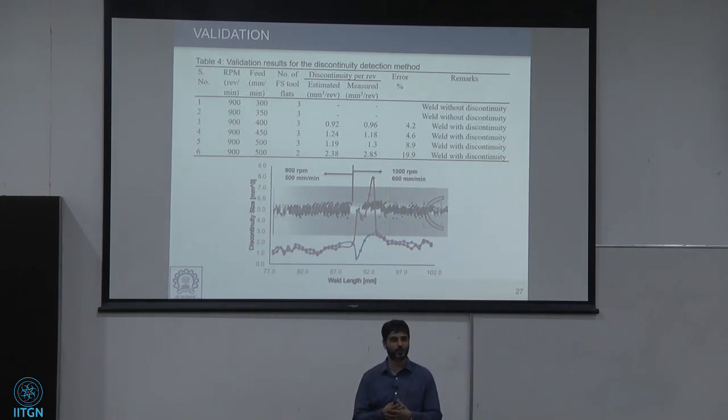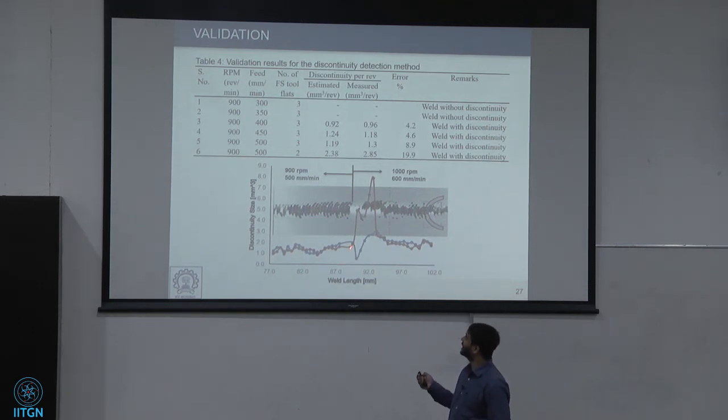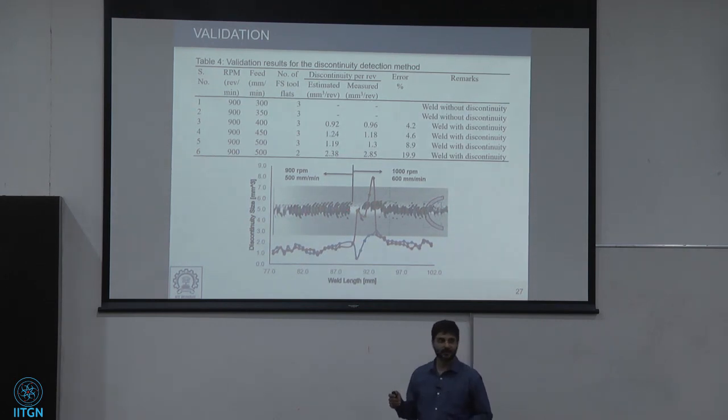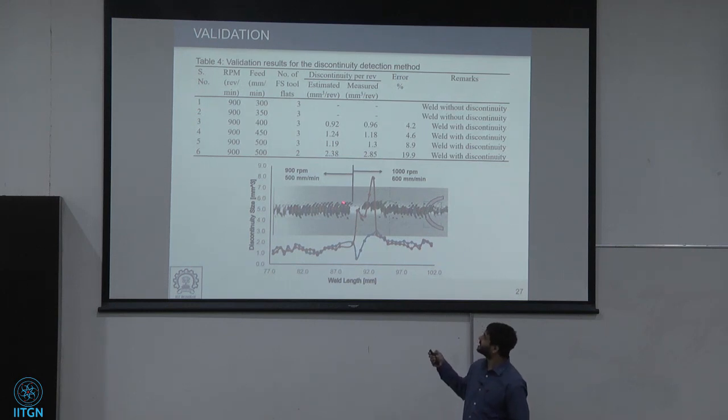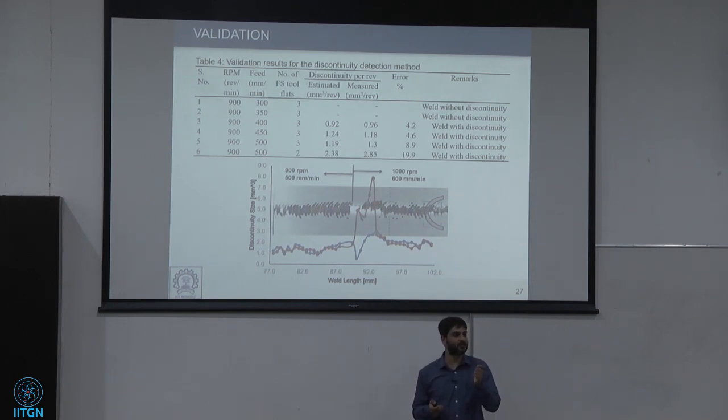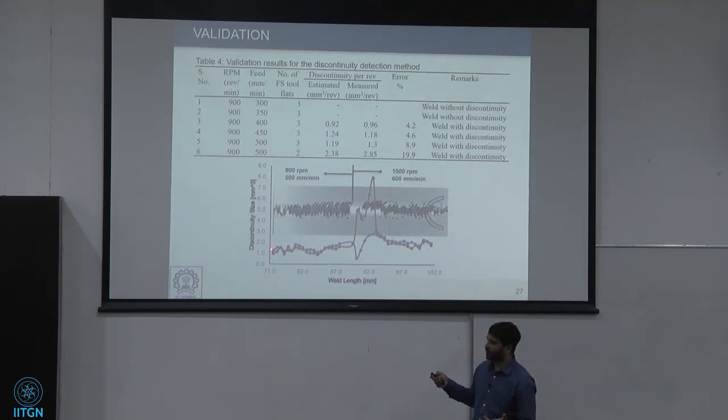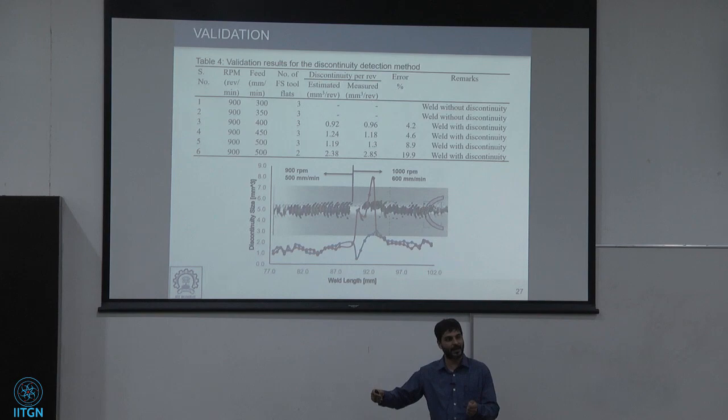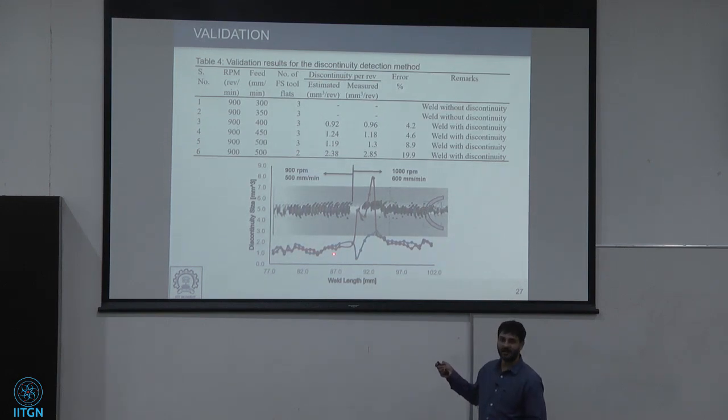Then, with the help of the observer approach, which was developed previously, we applied the same algorithm to the observer in real time, and we can see as the defects are formed. So for this particular weld, we identified in the CT scan a lot of regions of interest, ROIs, corresponding to the width of 1 APR, 1 advance per revolution. And what we could see is that the predicted size of the defect as the weld is happening could be captured decently well with the proposed algorithm. Now, in this very interesting weld, I wanted to see how the transition occurs.